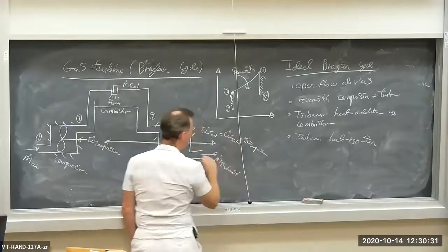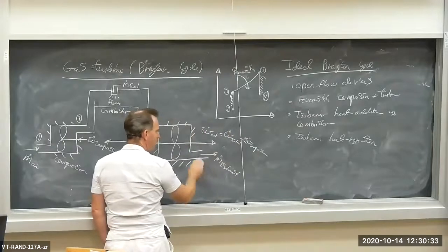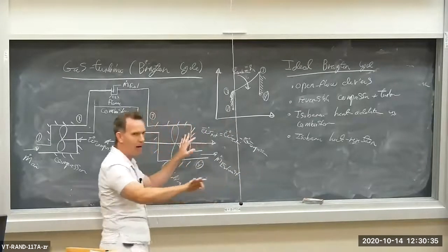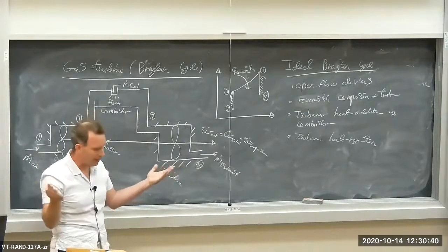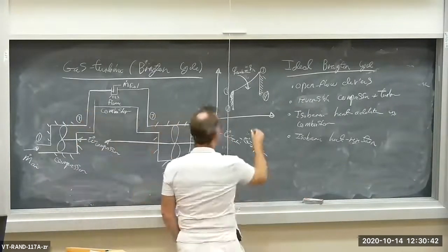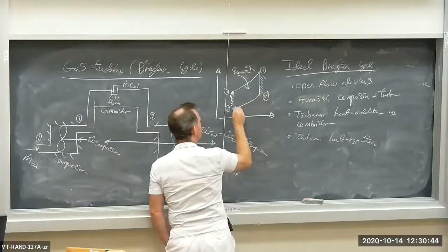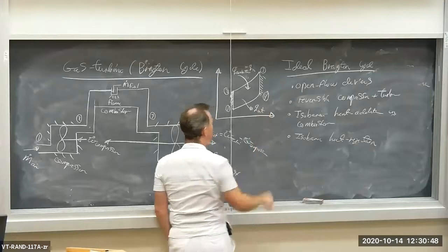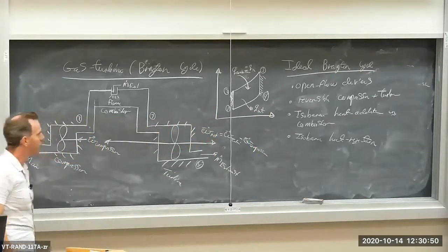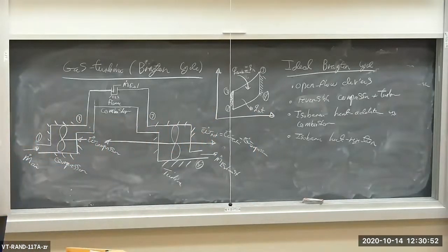The heat rejects, so the exhaust at state 4 is then rejected into the environment. The environment basically is at constant pressure, 1 atmosphere or something like that. So the heat rejection process is assumed to be isobaric. So we have Q out. We're not really interested in Q out too much. Q combustor or Q in is what we're really interested in.